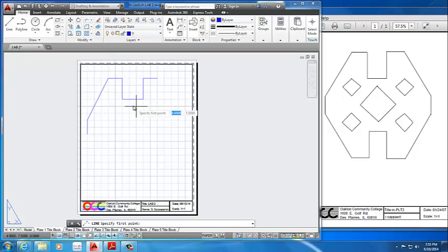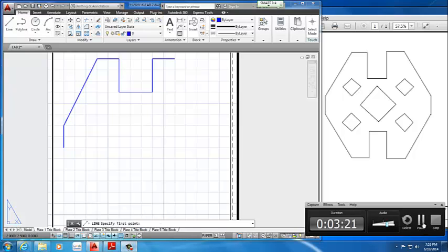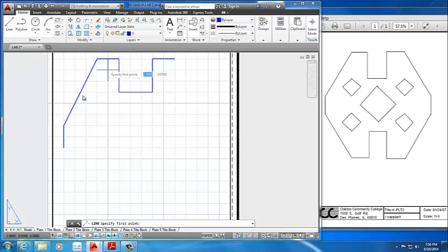I'm also going to work from the center. The problem with the center is I don't actually have the center spot. Some of you guys may have fallen into that trap. If you did 3 across, you won't be able to snap in the middle of these 2 boxes. How do you do that? For this one, that's a little bit tricky because we have to edit our snap mode to give us an option to click in between these lines so I can get the center of this.